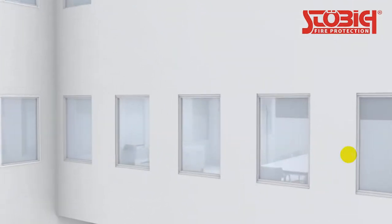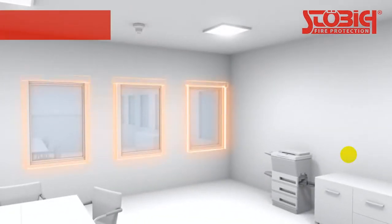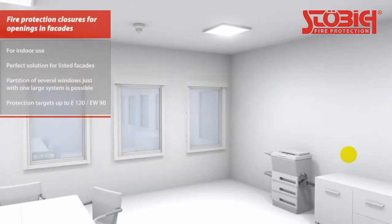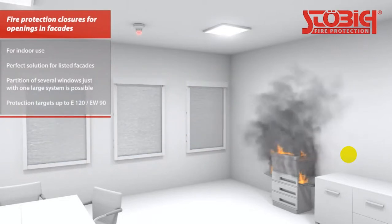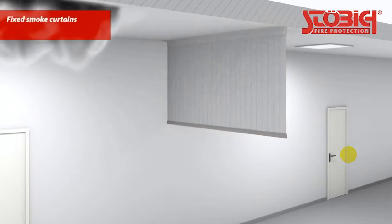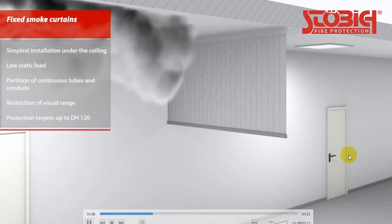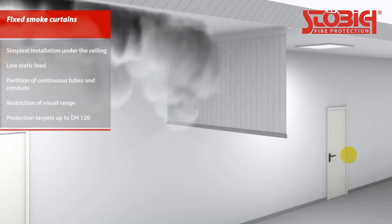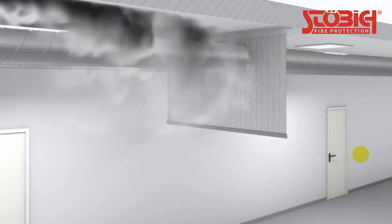As an alternative to partitions or compartmentalization in outdoor areas, openings between walls can be closed off using concealed fire protection curtains. This is often a particularly beneficial option for the facades of historical buildings. Smoke curtains are an integral part of any smoke control and dissipation concept, as they hinder the uncontrolled spread of smoke and gas within a given structure. Fixed smoke curtains are the simplest type of smoke barriers. They can be installed in unlimited widths and can even be used to partition continuous pipes and conduits.